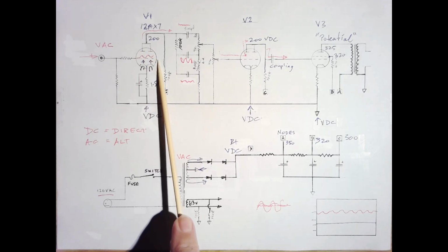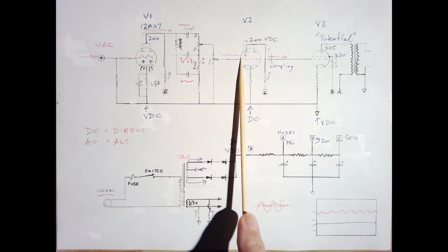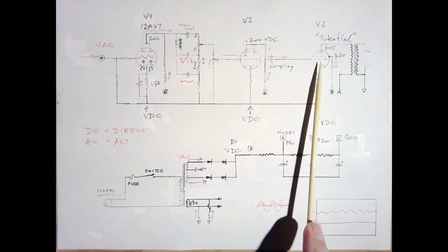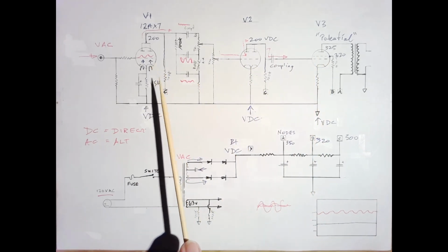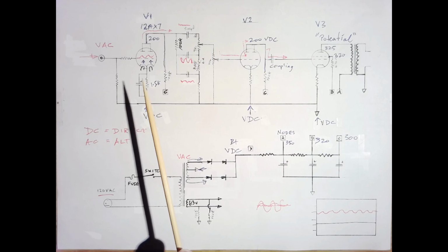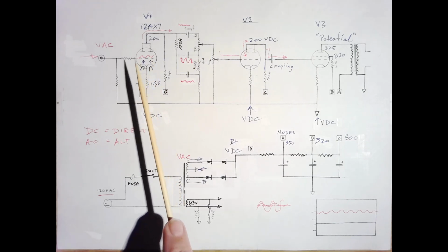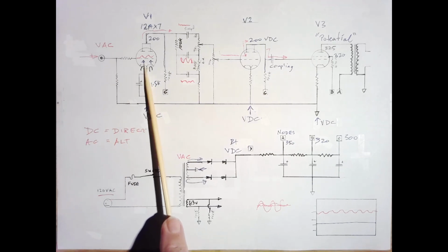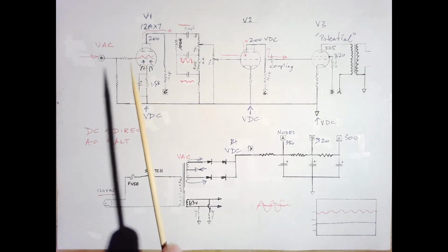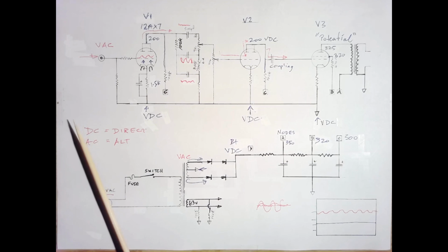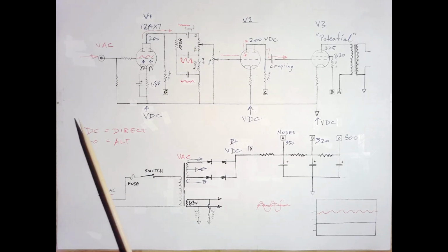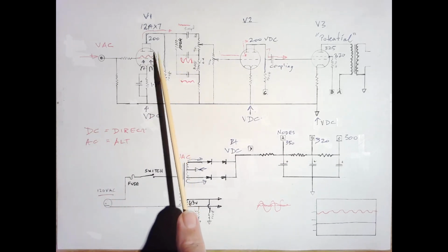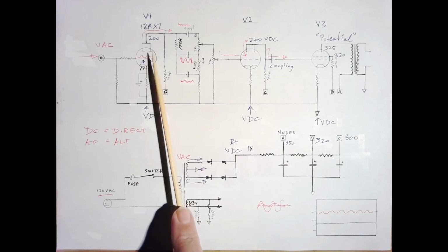And what we have happening in here is that tubes are vacuum sealed. You can tell when the vacuum is lost because quite often a tube will turn white on the inside, and the tube will stop functioning, because if you just have this DC current out in the ordinary air, there's a lot of resistance in the air and the DC will not travel through it. But through a vacuum, it's happy to go up to the plates.